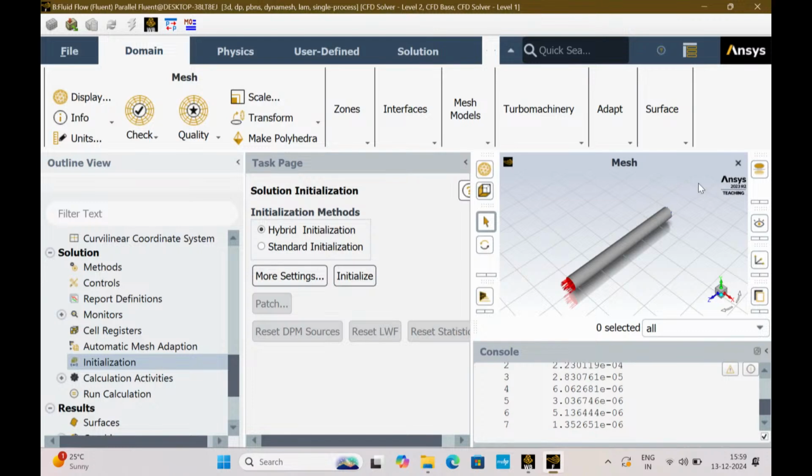So dynamic meshing, did everyone complete dynamic meshing? Click on dynamic mesh, tick on that box, select create or edit, choose wall from the drop down menu and click on system coupling. So that part was only different from yesterday's simulation, rest all are same.